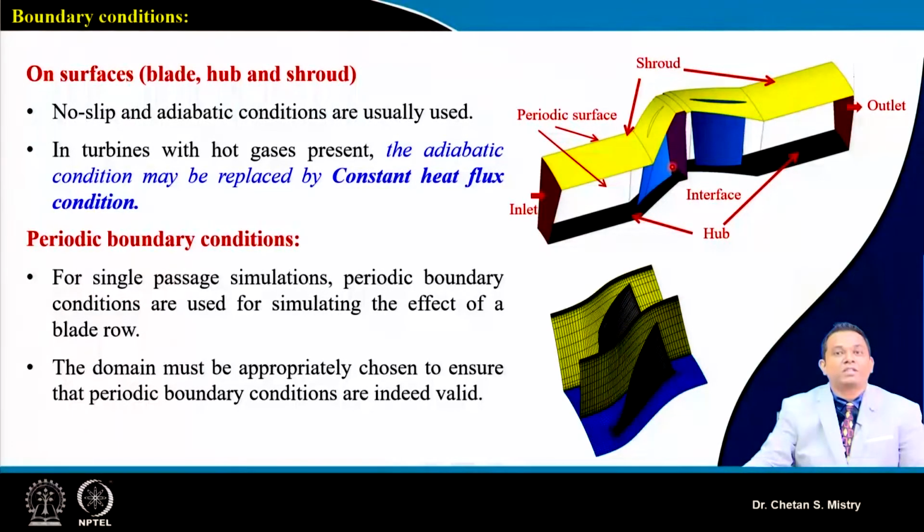We have realized the suction surface is very sensitive in terms of growth of boundary layer, because we are having adverse pressure gradient. So in order to capture all those details, we need to go with a no slip condition with adiabatic wall. Now many times when we are analyzing a heat transfer study, under that configuration, in place of an adiabatic wall, we need to go with a constant heat flux kind of configuration.